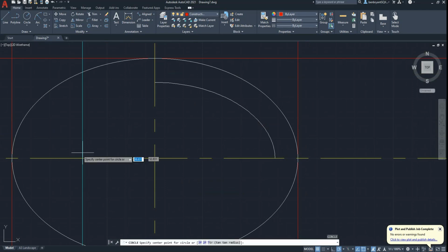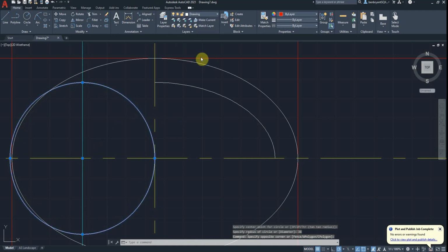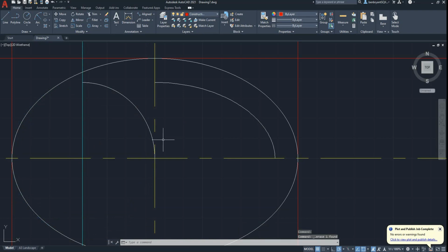From the circle, I'm going to put the radius in, so I know the center point's there and it's R38. Change that also to my drawing, and again I only need the one quadrant, so I'm going to break away that quadrant, then select the rest of it and delete the element, keep it nice and clean. Last off, there is a line that runs from this point to this point, which is an offset of 6 to build the 12 gap. So we're going to put that in, 6. I'm just going to delete that original line.